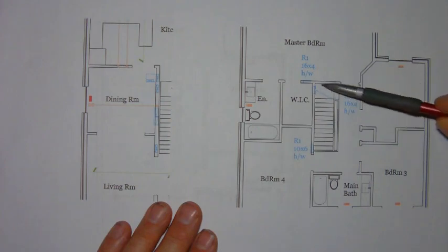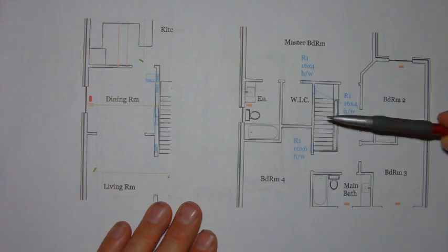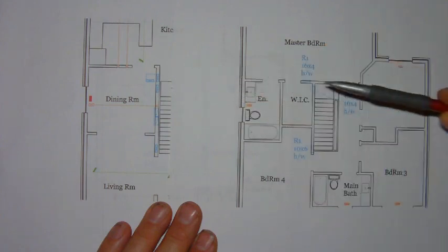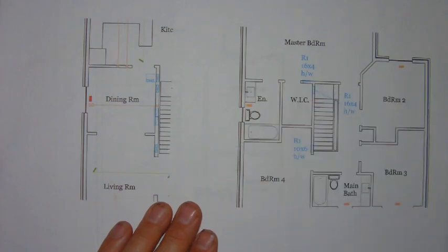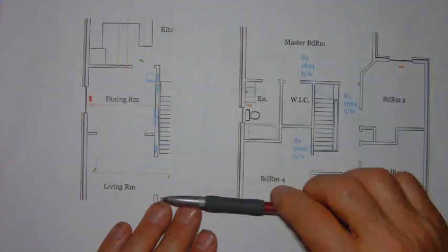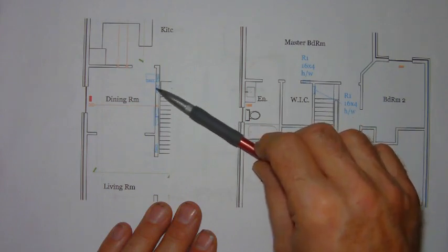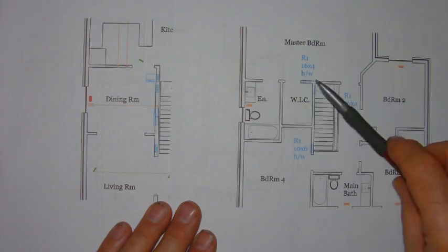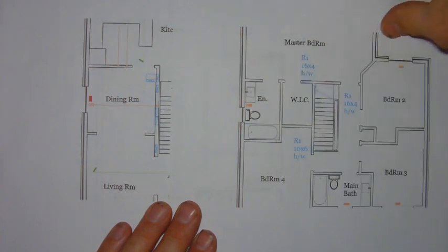Now fortunately we've got this wall here that is right beside the stairs, and typically you'll find in most houses that this wall will continue from the second floor all the way down the first floor, and so it tends to be a very good wall to use in order to get second floor returns down to the basement level. And so we can see that we've got these three returns fitting in nicely. So that means we can get our second floor returns down into the basement.